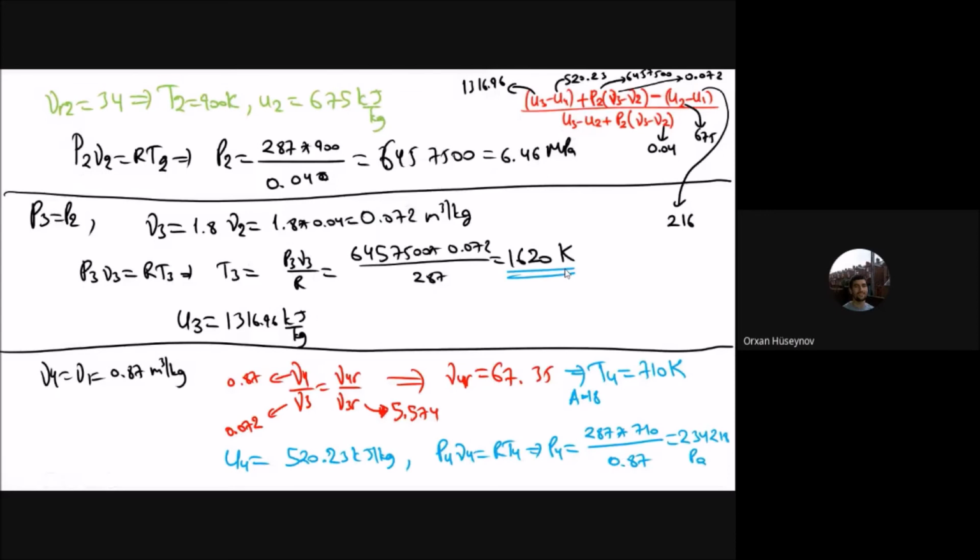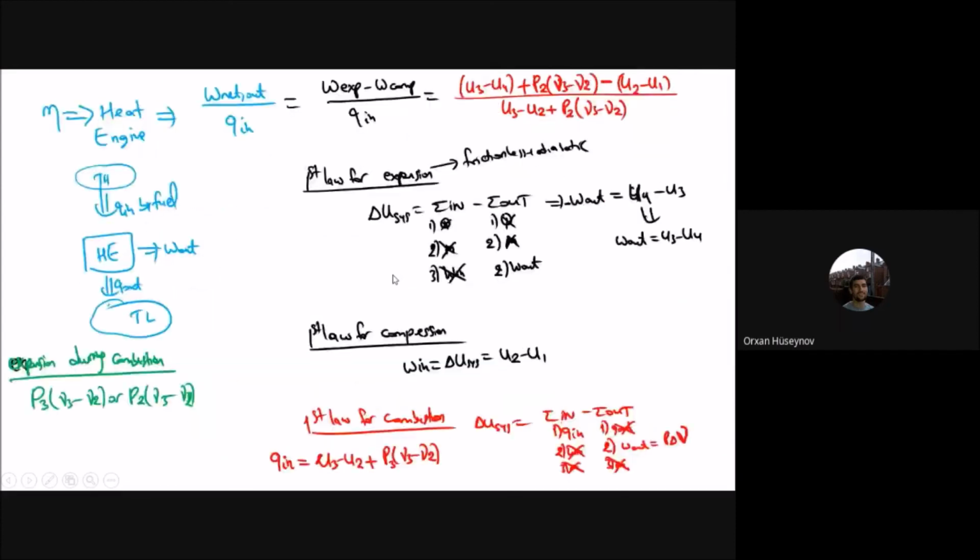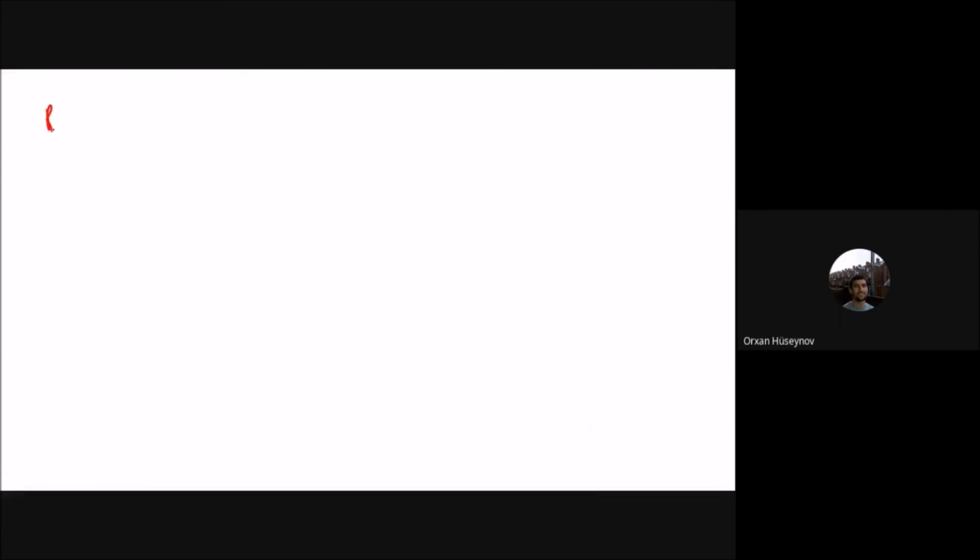So let's calculate it and tell the final result. I've said that this is 0.55. 0.55 is the efficiency of the ideal diesel engine. You should remember this one is ideal, but in reality, a real engine has 3 parts: 1/3, 1/3, and 1/3 here. This 1/3 part is the efficient part in real, where you get the power. But the rest, this one and that one, are losses.